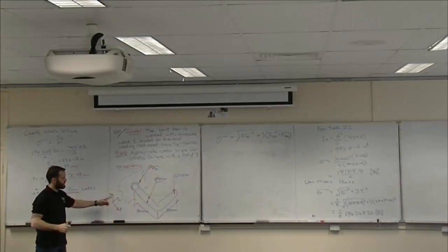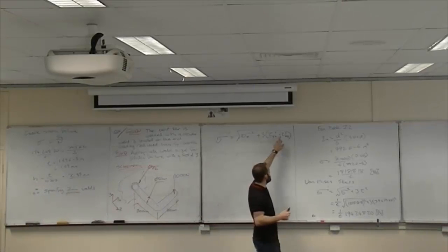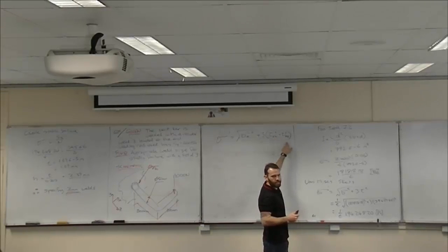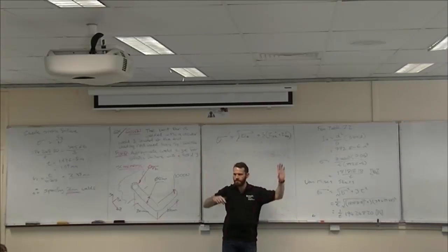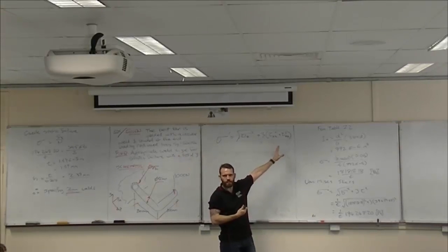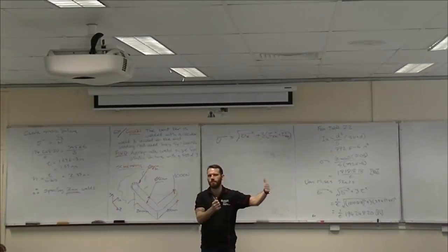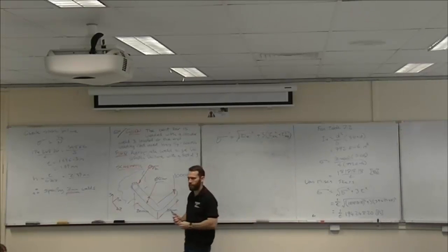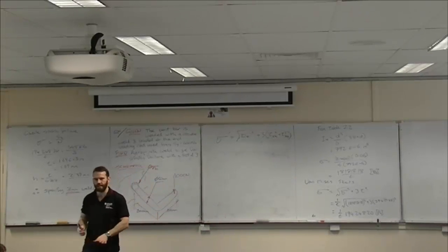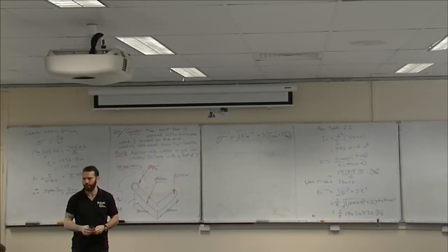Now remember that those are the coordinates that actually line up with the Cartesian coordinates, those two shear stresses. This isn't primary shear and secondary shear. Primary shear and secondary shear are vectors, and so they can be close together or far apart or whatever. Once you have primary and secondary shear, you boil them down to their x and y components, and then you add all the x's, add all the y's, and substitute results into those 2 points. Okay? So don't get mixed up and just accidentally throw primary and secondary shear into that equation, because it won't work, it'll screw everything up.